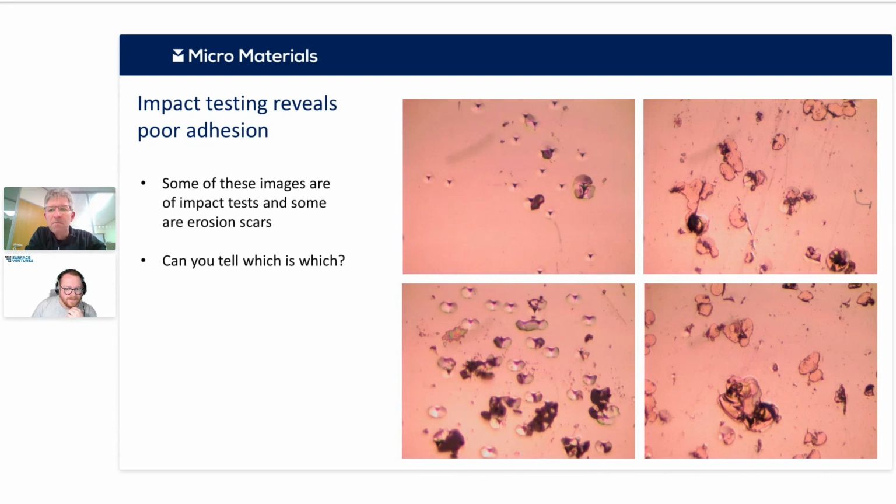Yeah, in erosion of TBCs, with alumina and things like that, you don't tend to have these sort of mechanically mixed layers. You may get that with silica type erodents. So the answer is, how would we do it? We'd maybe have different types of indenters.